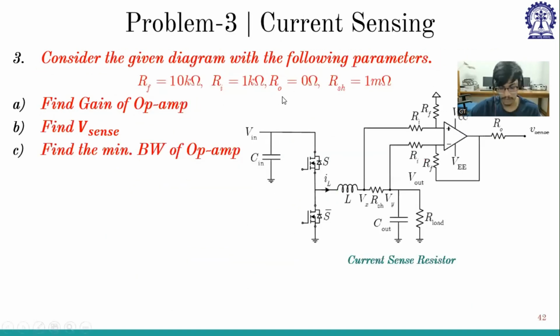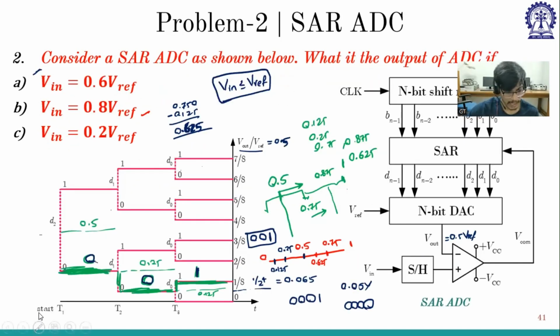say, I have shown you one ADC, right? The ADC that we have used. In that, you have seen either it is 1 volt peak to peak or 2 volt peak to peak. 1 volt means it can go from -1 to +1, right? So this 1 volt is V reference because V in cannot cross V reference. So whatever V in I choose, it will be a fraction of 1 volt, right? So that is what V reference is.